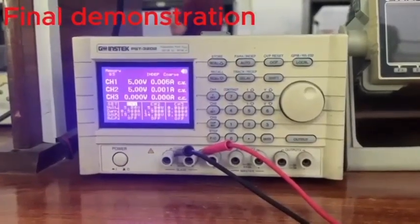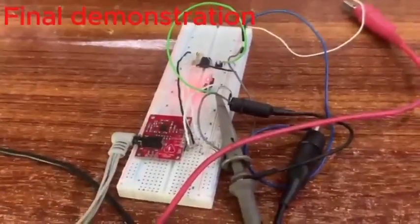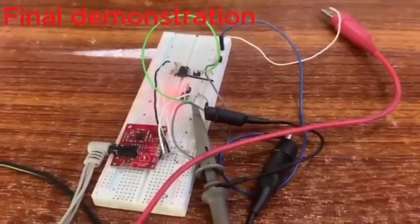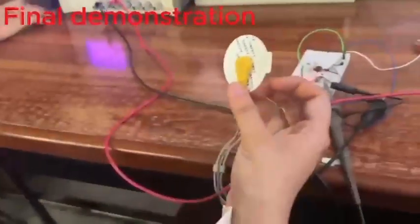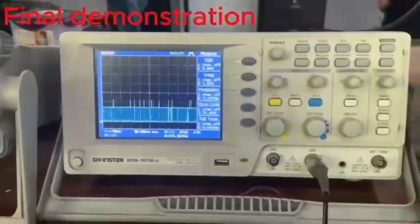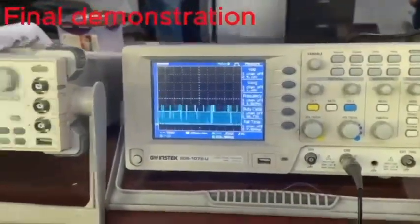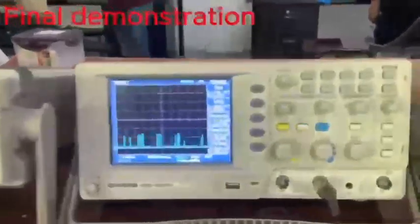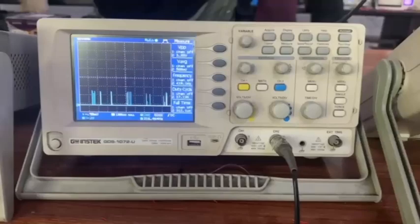Power supply was given to the circuit according to the connections on the breadboard, and the oscilloscope wire was also connected to display the output. As you can see, the electrodes were already attached. The main part is that you get the peaks that you need for your HRV analysis when the electrodes are placed. But to truly test whether your circuit is working, you can take the electrodes off the skin, and it will show a distorted signal. As soon as you connect the electrodes to your skin again, the peaks will show. In this way you can do your HRV analysis.